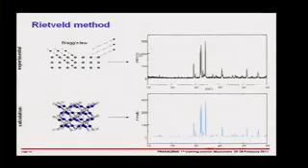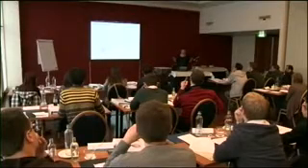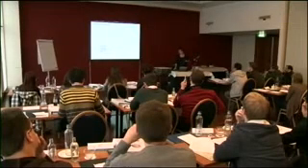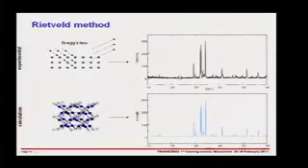If I go back to a spectrum like that, you see, okay, you've got this kind of variation in the background, and therefore it's a question of what's your signal-to-noise ratio. Okay? So if you do your scan slower, so if you acquire your diffractogram over like 10 hours rather than 10 minutes, then you'll get much less background. And then even if you've got quite small peaks, that may be enough to detect it. But it doesn't help much because we've got just a huge, huge amount of aggregate.